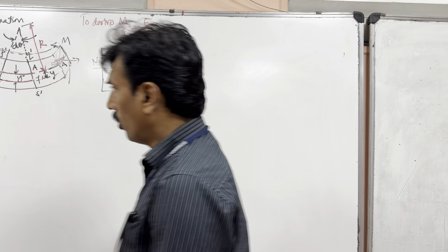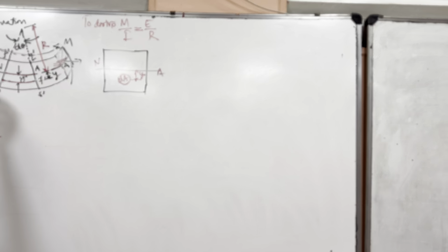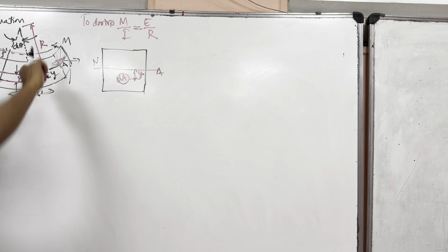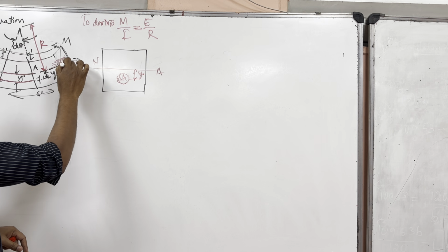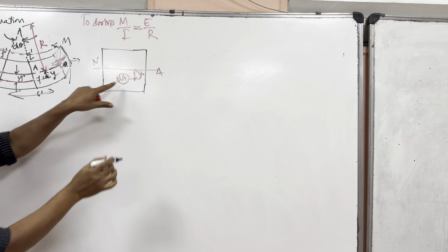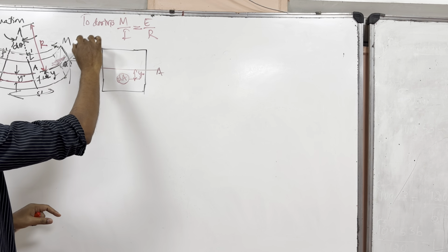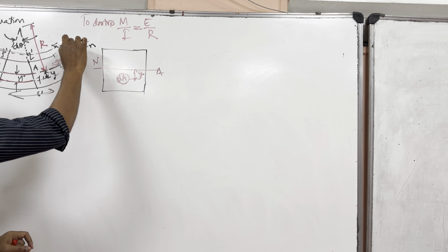Okay. Now you know that since this material is bent like this, here you will have the tensile forces. Here you will have the compressive forces. Now, suppose if this area is here, suppose if the same area I am showing here, you will have a force which is actually tensile, which I call the normal force Fn. That is the force at a distance of y from this neutral axis.